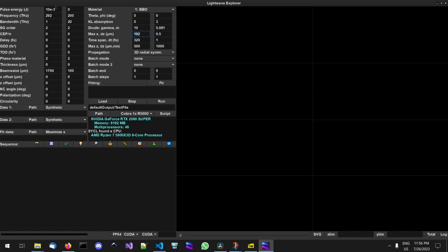So you can see I have a big spot size, so I'm going to use about an 8 millimeter grid with fairly coarse spacing, but good enough for a demo simulation. I'll give a picosecond for my time grid, and use a half a femtosecond step, which should be good enough for what I want to show. And for setting up our test calculation, I'll first start with a fairly thin crystal, and we will do it again in 2D Cartesian mode.